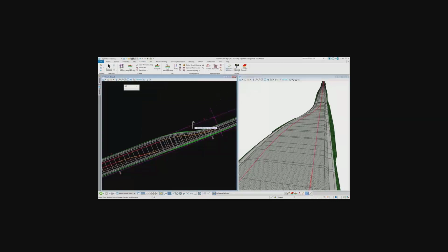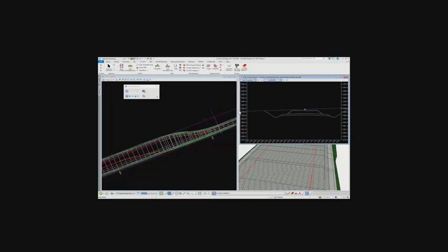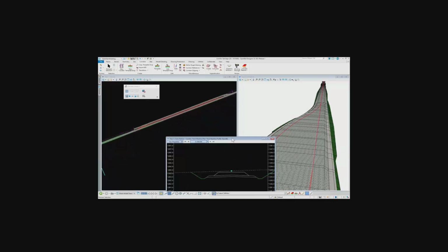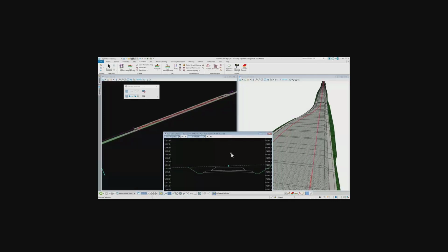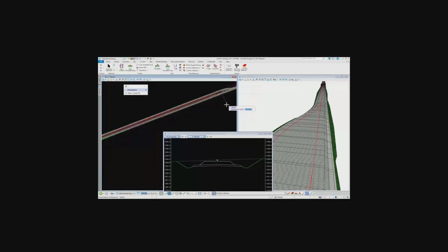Looking at it in cross-section view, so that more or less you know what just happened there. In the cross-section view, you will be able to really see if the point control that you applied was actually applied properly. So let me just adjust the cross-section view to shift to this turnout location.